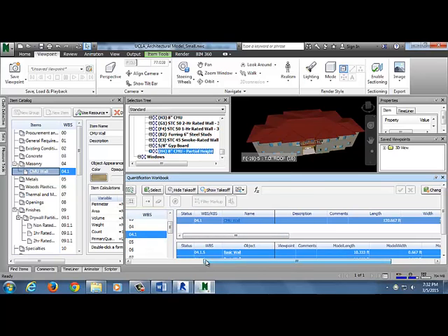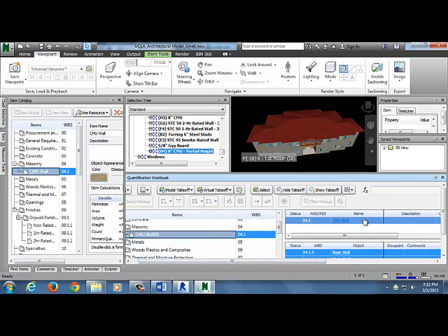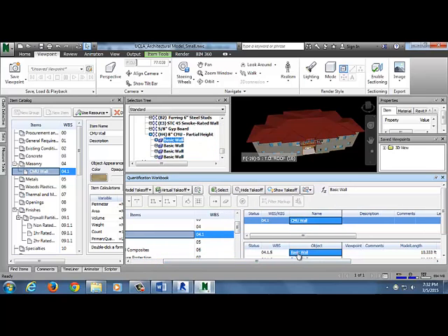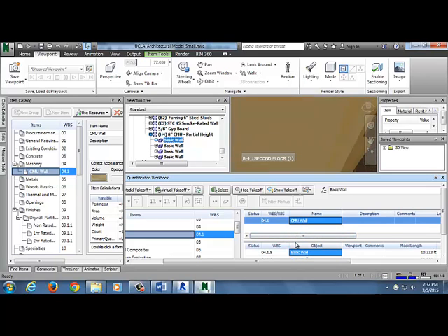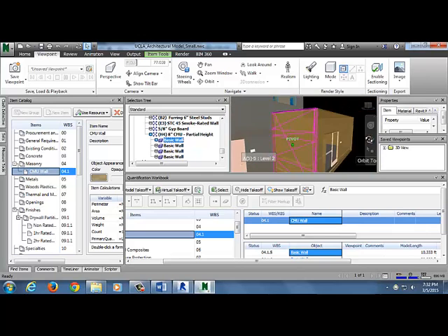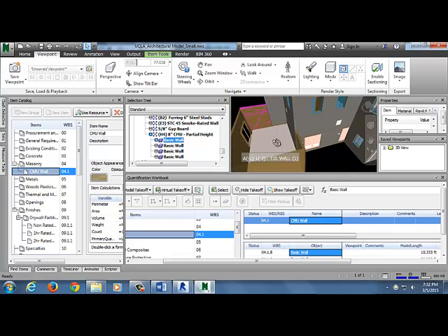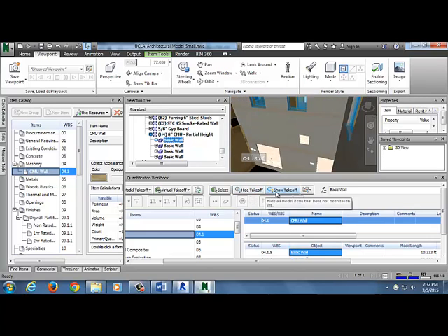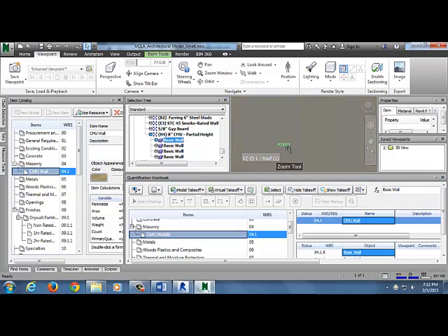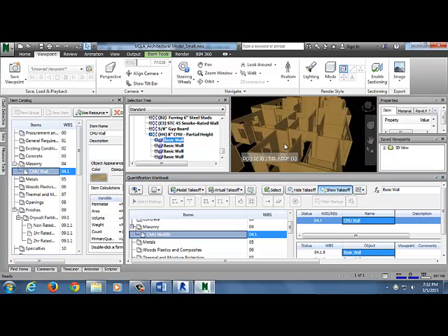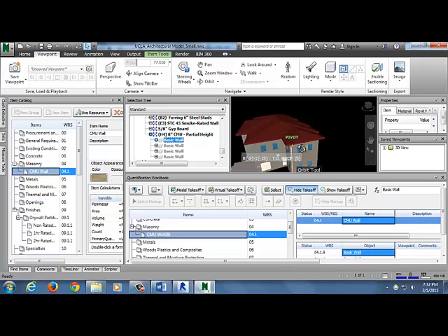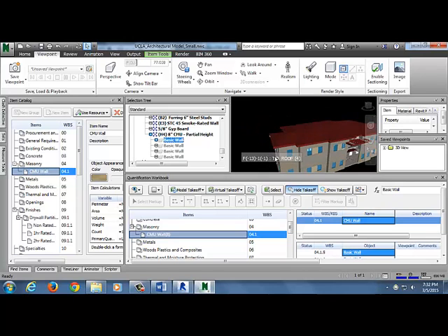And if I click on an item here, you can see, if I click page down now, since I selected that item, it's going to zoom in to where that wall is. And you notice that it shaded things. I could say show takeoff. So everything else now should be hidden that I didn't take off. Hide takeoff, so you can see all the things that are still there.